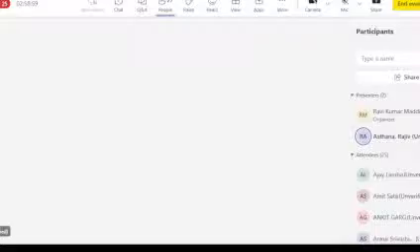Another process uses powder extrusion. Very simple process like clay extrusion. If you want to make parts of ceramics with very fine holes, you use extrusion. So this is one extruder in which you put your ceramic powders, the liquid binder inside. Either use a screw to push that slurry right here, or you can use piston mechanism. The screw mechanism will give you a continuous process. A piston process will give you batch type process. So depending on what you want, you can use those mechanisms.